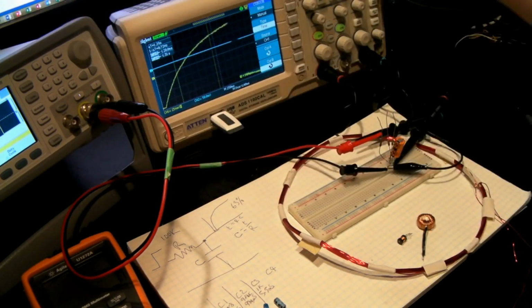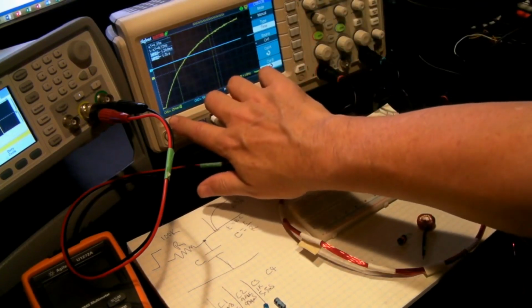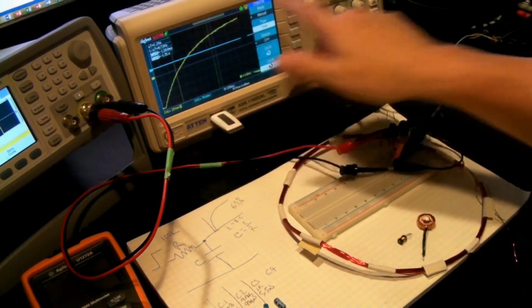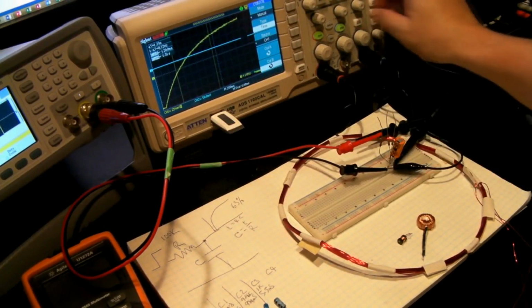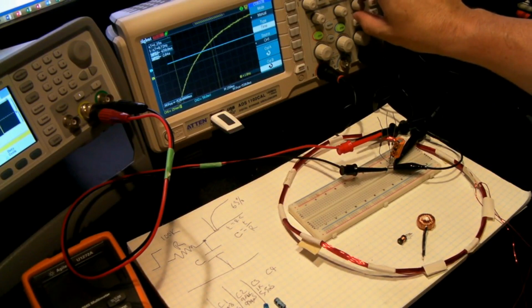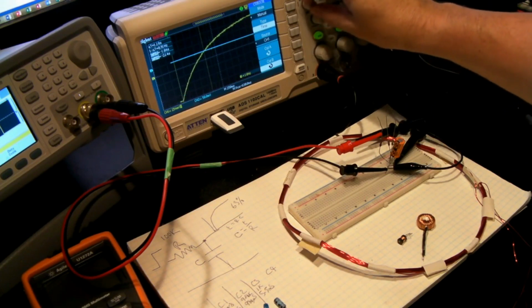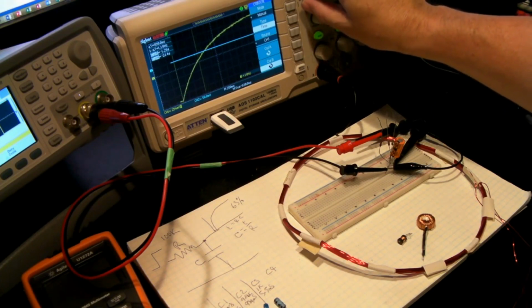So what I'll do here is I'll stop it as it's already gone through. So as you can see here, I've just stopped it, but it's actually already gone enough of the trace so that we can do some measuring. And I should be able to just slide this across to line it up with the cursor A. Okay, and now I'll adjust cursor B to hit the intersection.